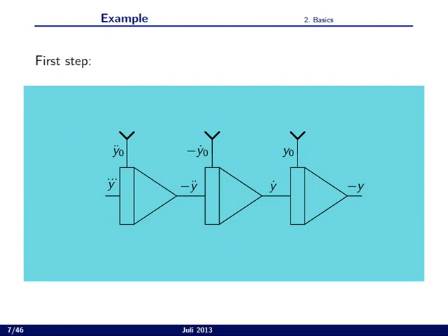And integration is astonishingly simple in an analog computer. You have computing elements that implement integration. Most of you will remember integration as some kind of hard operation from mathematics from school. That's not true. Integration can be very, very simple. Collect water in a bucket. That's integration. Collect current in a capacitor. That is integration. Count bits in an accumulator. That's integration. So it's simple to build an integrator.